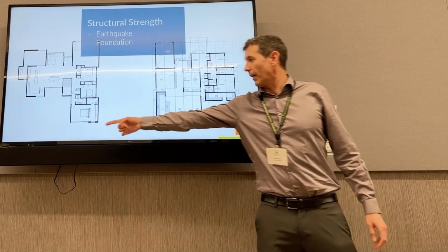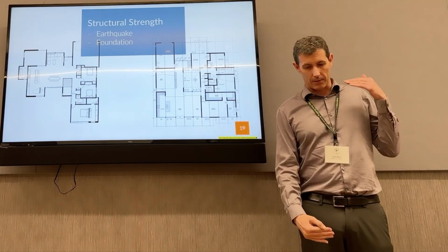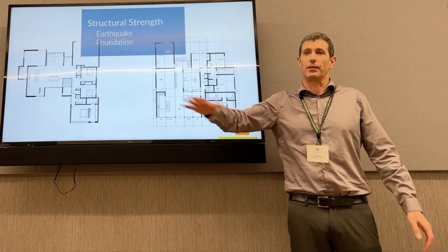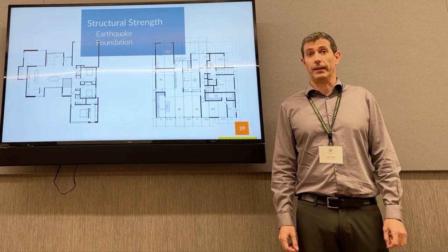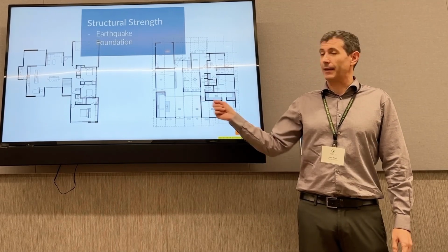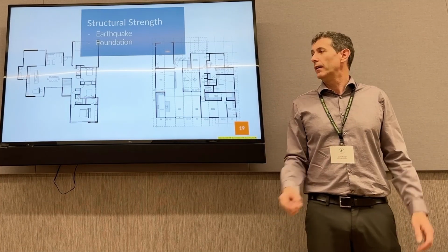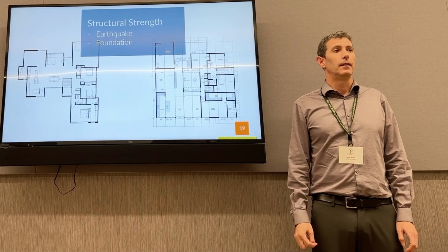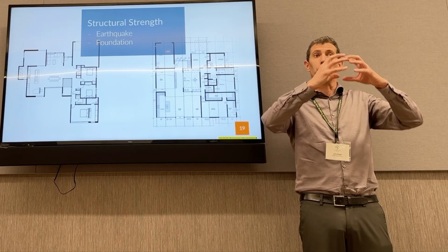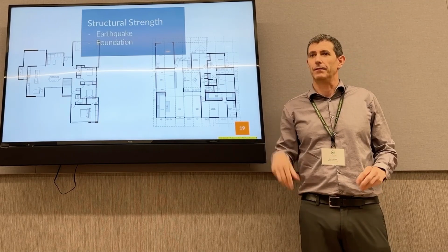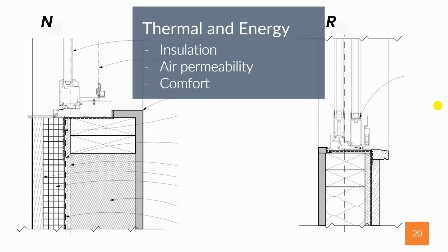So this house, on the other hand, has an engineered foundation. It's not on piers, it's in a flat lot, but it's a very deep structural spread footing. And this house, depending on where it's located, is going to buckle and warp and subside and so forth. This house will not. And if it does eventually start to sink into the ground, it will sink uniformly because the foundation's been designed for the soils on the site. Next slide, please.